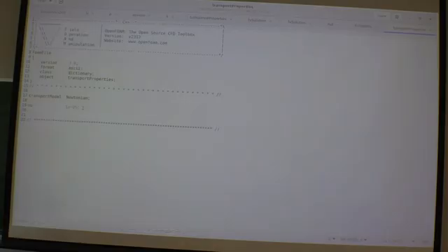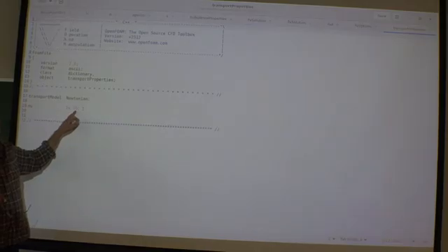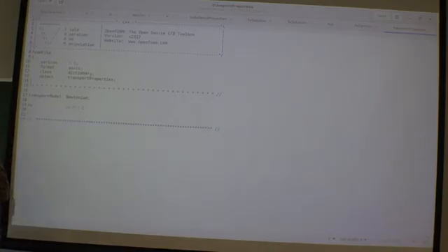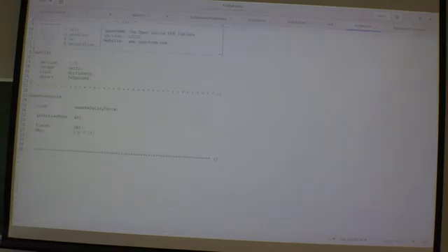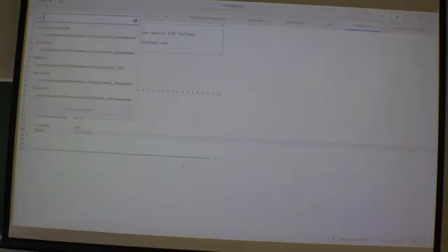So this one is 10 to the power minus 5. I have an opening of 1 meter. I have an average velocity of 10. So I have a Reynolds number of 1 million. Ooh, that was a little bit too much, wasn't it? Let's reduce it a little bit. 4 there, and then save. And for the U, no, not that one, sorry. The FV option, I go back to 1. Then I should have a Reynolds number of 10,000. It's a little bit more soft.